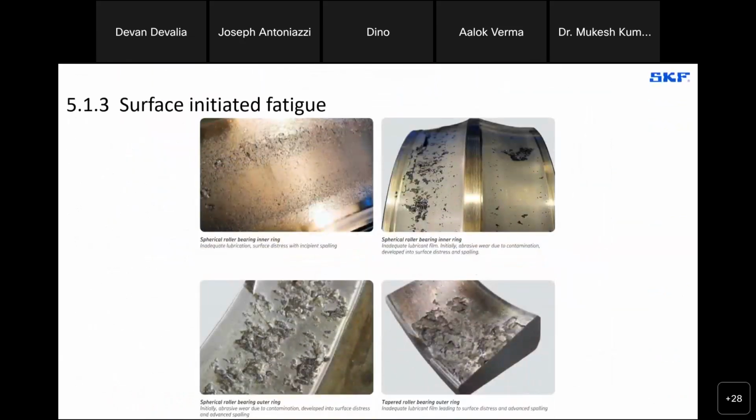So back to the pictures here, and what we see is a lot of spalling, and note there's wear as well involved. I'll discuss this further later, but we will see layering, different types of damages on top of one another, interplaying with one another, because imagine when you lose material and you have this material floating in the bearing cavity, there will be wear, and there will be more damage, and it's a cycle that just worsens until catastrophic failure.